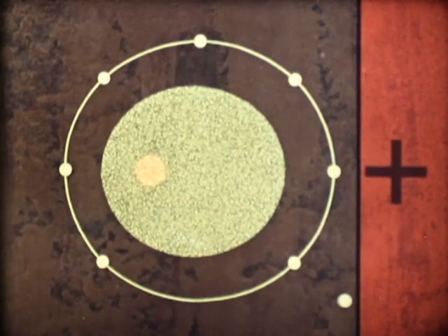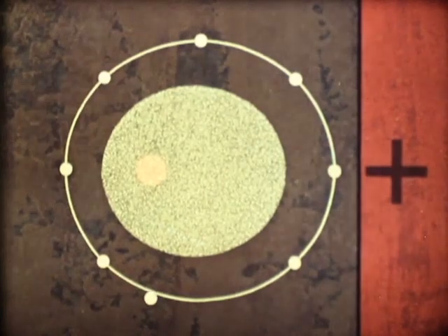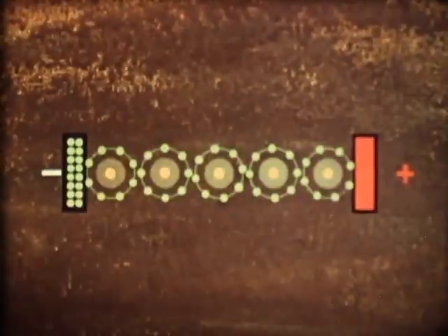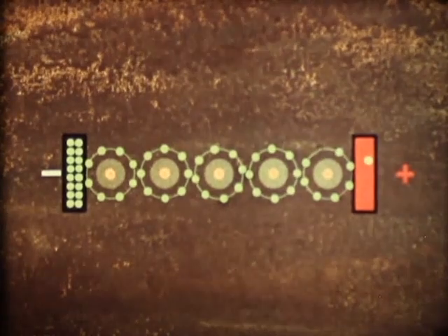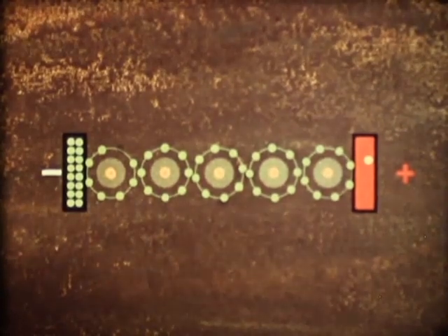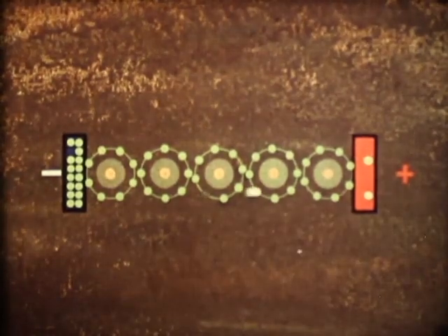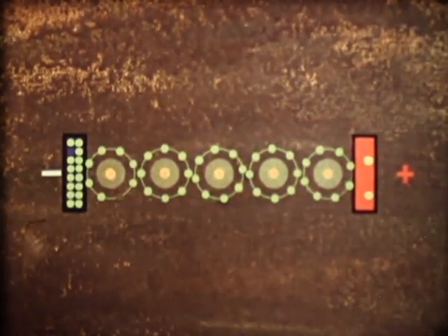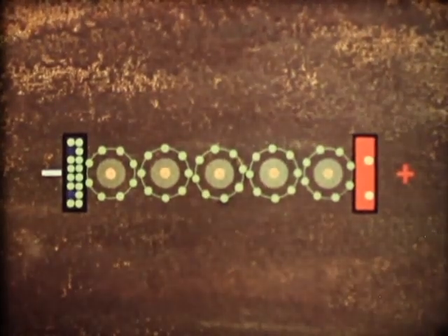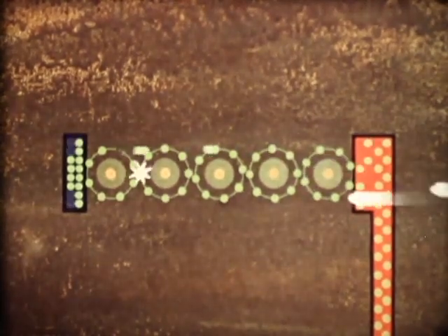The vacancies left by the moving electrons are in turn occupied by electrons from neighboring atoms. This can be clearly seen from the diagram of one of the small charged capacitors. The last vacancy will be occupied by an electron deposited earlier by the electron beam. The electron deficiency at the left is regularly replenished by the passing electron beam. Simultaneously at the right, an equal number of electrons are returned to the battery.